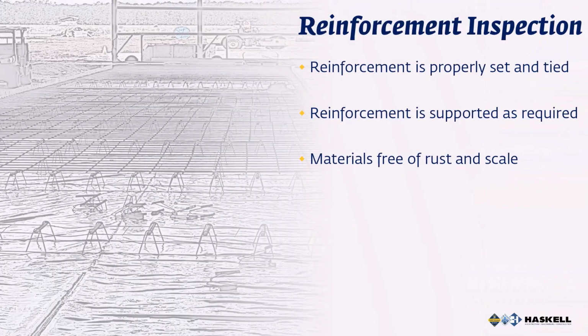A check of all reinforcement includes the following details: reinforcement is properly set and tied. Reinforcement is supported as required to maintain proper depth and cover. Materials are freed from rust and scale.